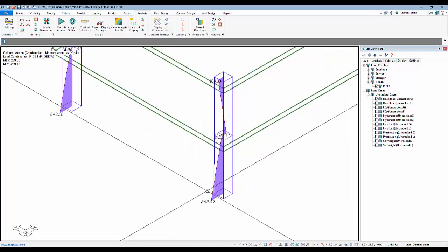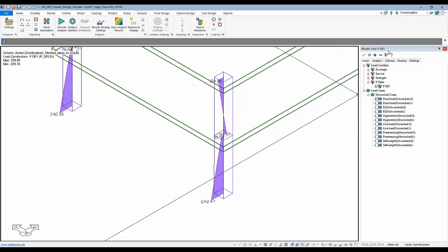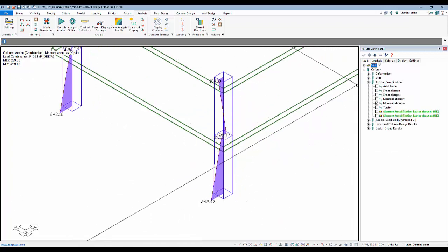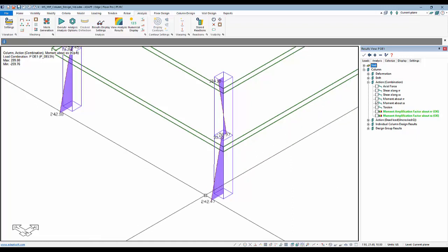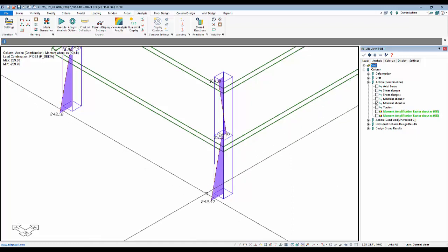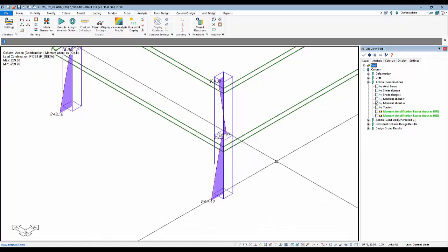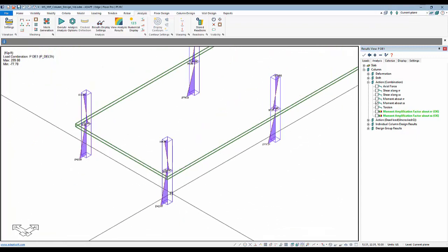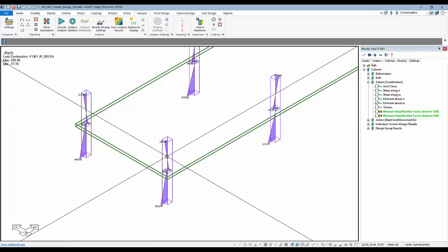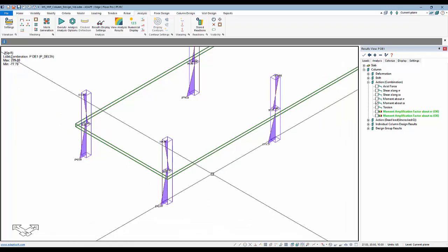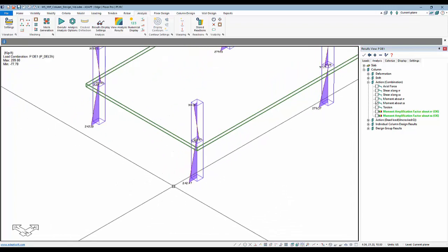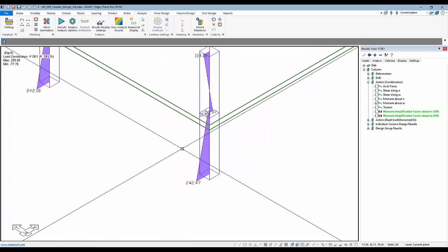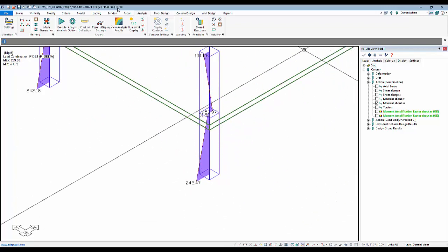Okay, so the moment for PDelta globally is going to be, moment about SS is 242.5. Okay, now I'm going to go back to single level. I just had to come back and do that to get that force. It wasn't stored graphically because my last solution was single level. So I didn't want to have to dig through the text file to find that. So now in single level, I'll rerun single level again.